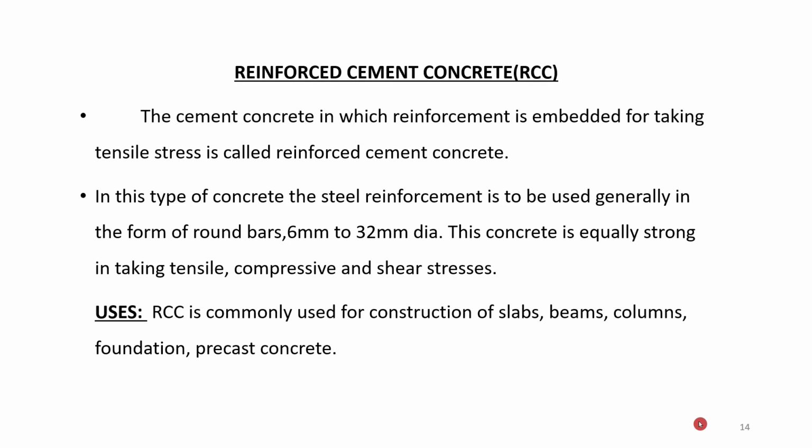Reinforced cement concrete, I already told, we are reinforcing the concrete so that it can take the tensile stresses. Normally, we do it using rebar ranging from 6 mm dia to 32 mm dia. These are commonly used for slab, beam, column, foundation, where both compressive and tensile stresses are happening due to the bending of the structure.